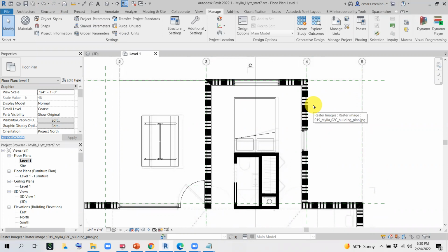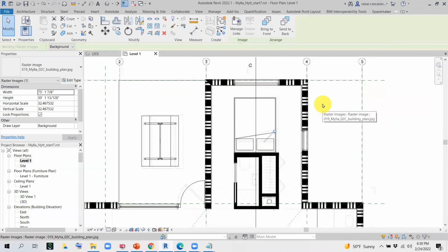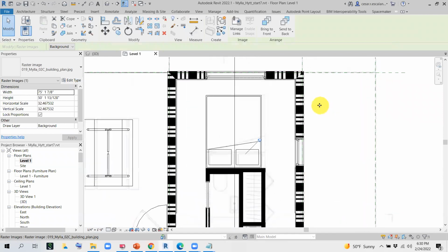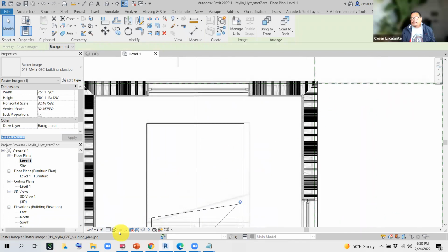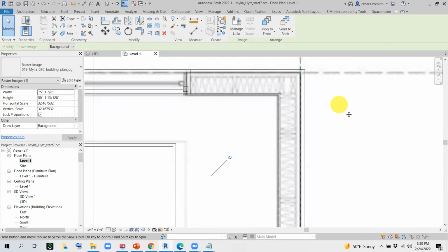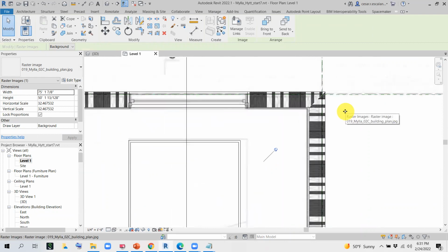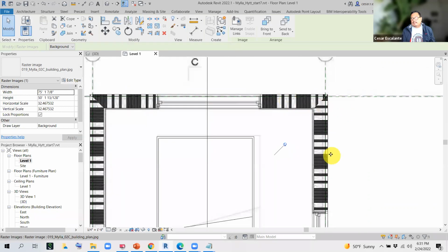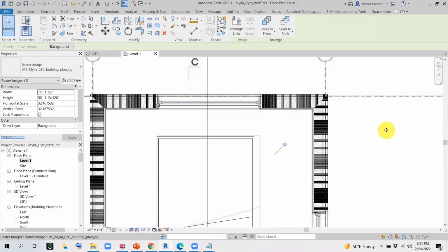Yeah, for some reason, my lines are not reading as black. There's like something on top of it. So make sure you are on wireframe, yes. And also make sure you are on coarse view. Yeah, I'm on wireframe and coarse. So you're still not seeing it? Oh, you know what? I think I might have made it white instead of black. Maybe that's why.